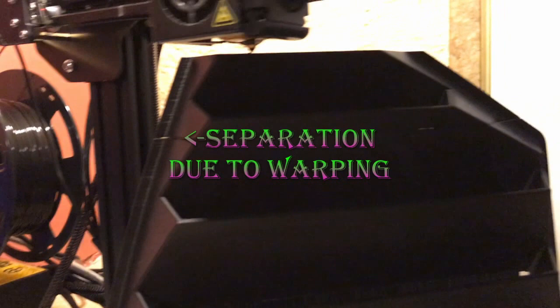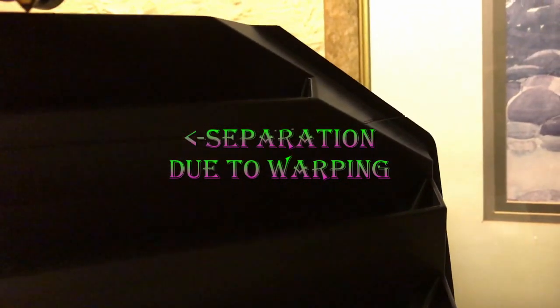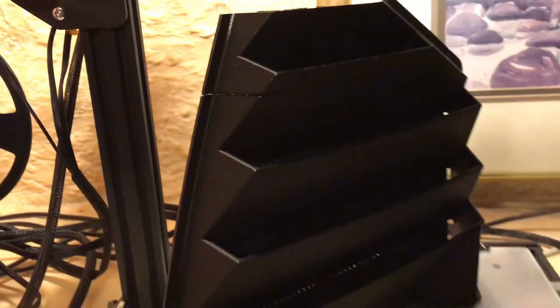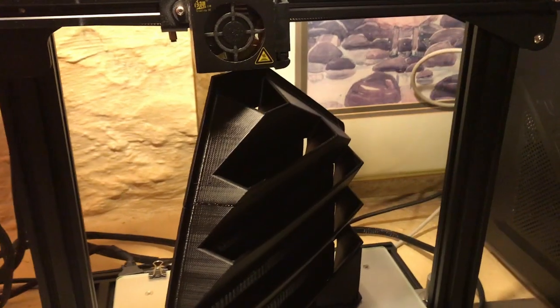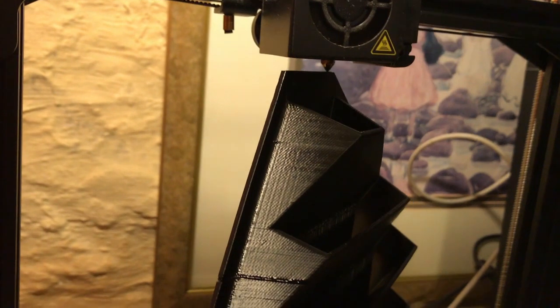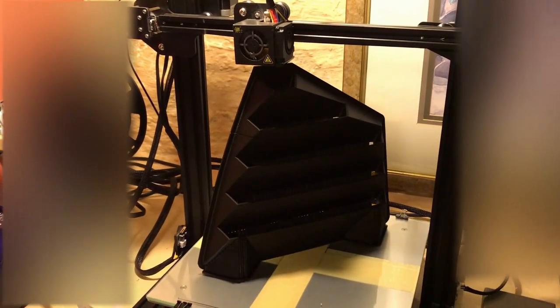My first print started strong, but eventually turned out less than perfect as it had material separation brought on by excessive shrinkage of the ABS plastic. I had an open air system, and although okay for PLA plastic, it wasn't the right environment for printing large ABS plastic models. I knew after a few tries that I would need an enclosure to keep the plastic from having extreme temperature fluctuations during extrusion, and in return increase the chances of a successful print.